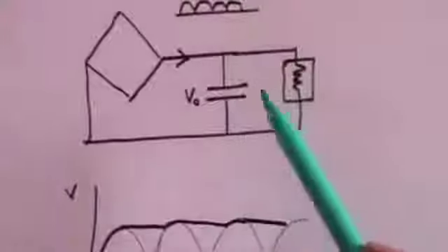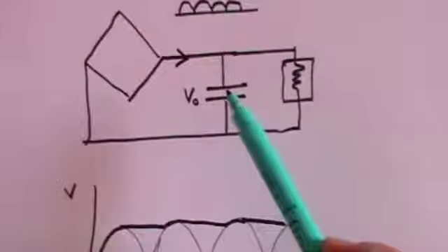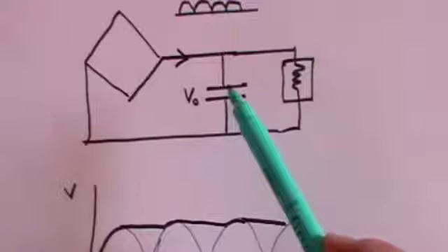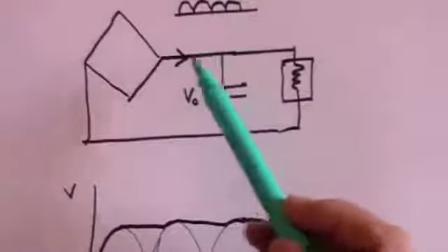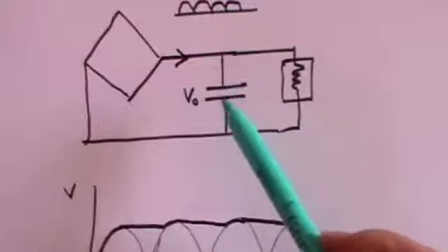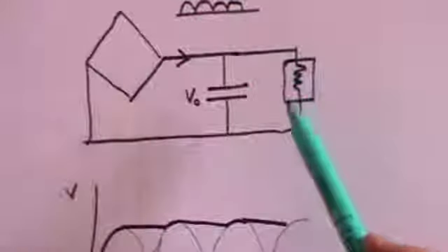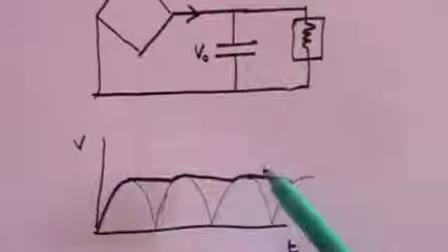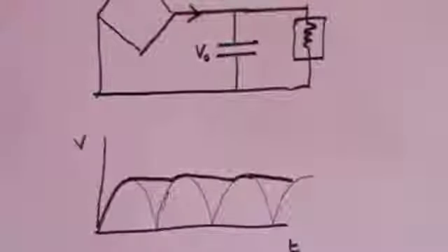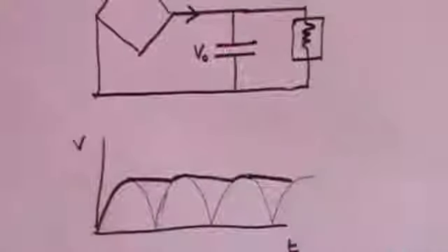So what you need to do is to put a large capacitor, which will charge up to a maximum voltage of V0, but it will slowly discharge, and that means that as this alternating current varies, the capacitor acts as a DC supplier. It effectively becomes a battery supplying a DC supply whilst the current would go down and back up again. It can smooth out that voltage and thus provide a pretty much constant voltage for the computer.